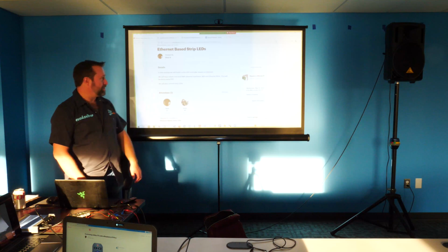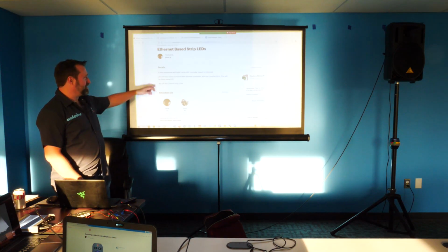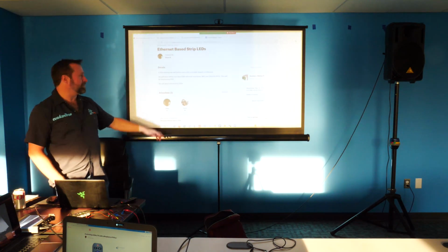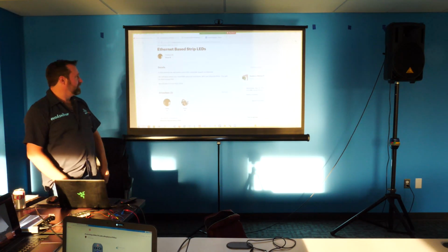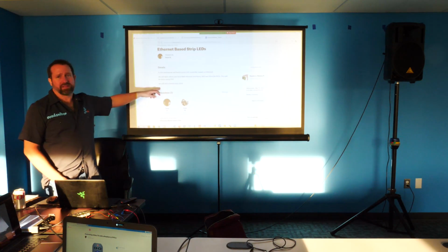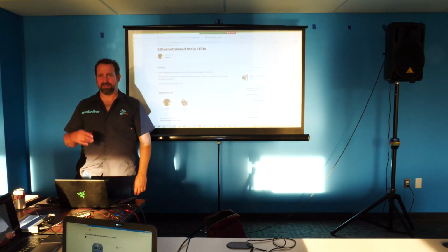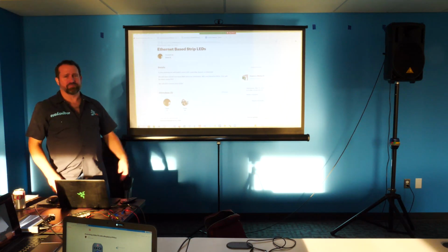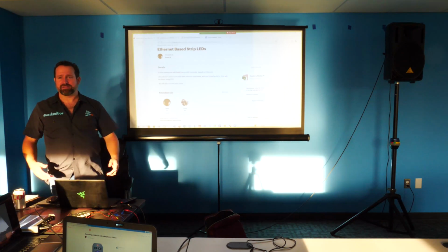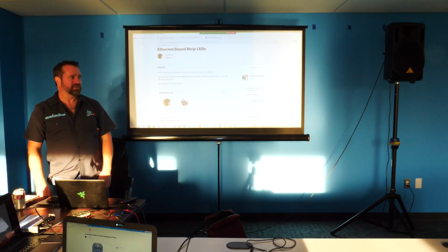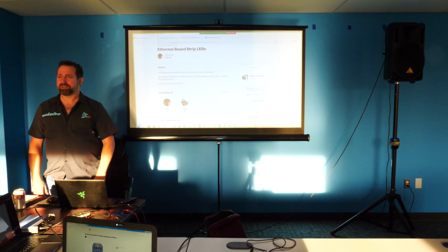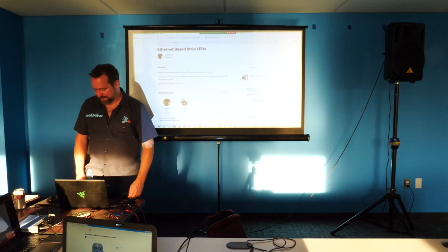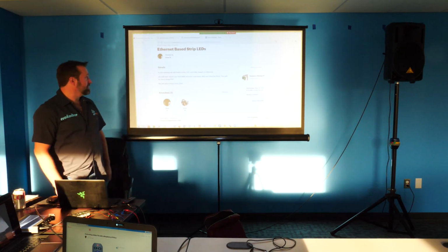I don't know if we'll do a custom board. There's actually an Ethernet board available that I might be able to buy from China for $2, so I'm going to try to use that before the meetup. We might do a small board for strip LEDs, just because usually they're 5 volts. You can get them in different voltages, but since you need to put some translators and stuff, and since driving strip LEDs is super fun, and you can think of probably 1,000 projects you can use it for, it'd be cool to have a little board that makes it easy to use, makes it easy to do.